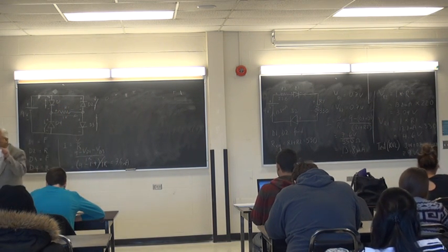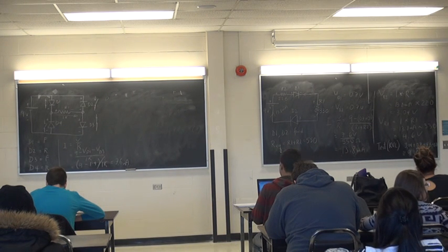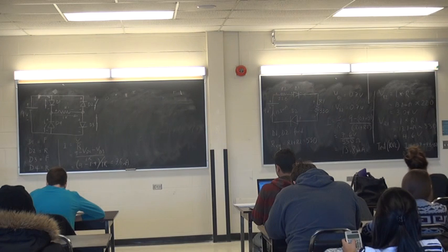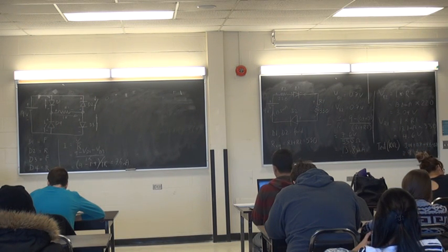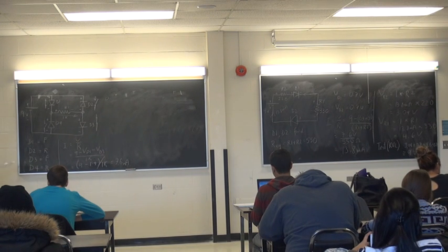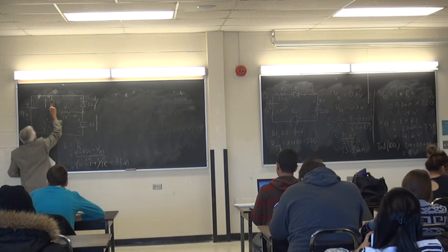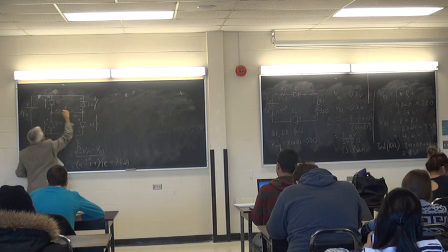First, the voltage determines the behavior of the diodes. And then current will flow through the diodes that are forward biased and not through diodes that are reverse biased. So the current is actually flowing over this way, it can't go down this way, so it goes through here.